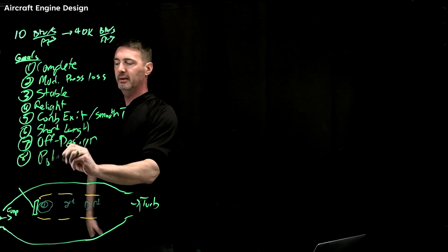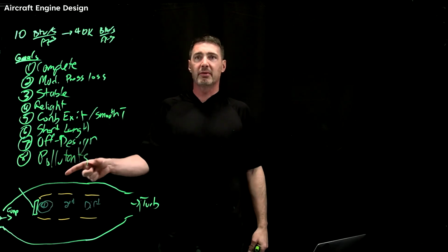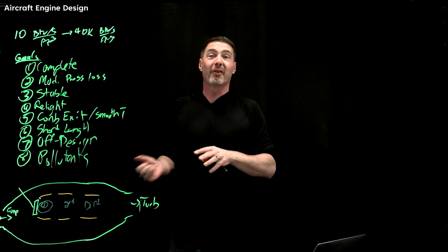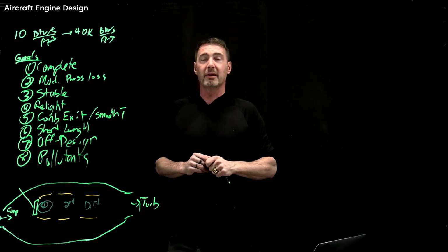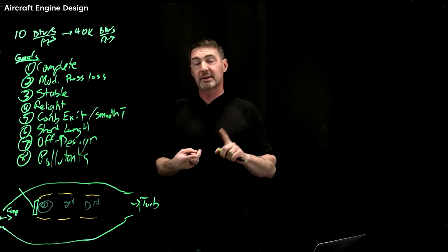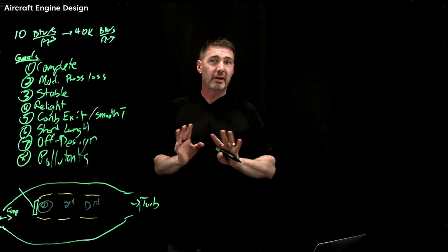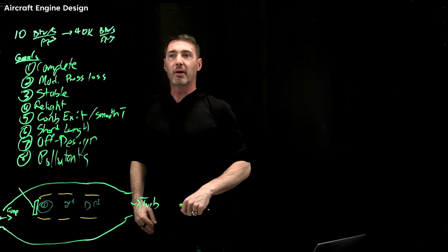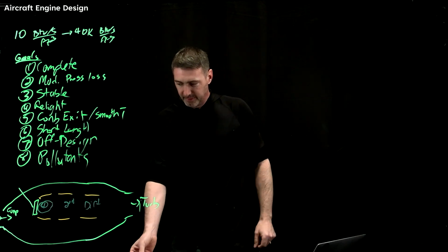Now, I know recently there's been quite the interest in CO2, but just to remind everybody, our interest about 30 years ago was all about NOx. And so that is still a requirement. We are still interested in NOx reduction because of our ozone layer and things like that. And so it's really this combination of generic pollutants. It's NOx, it's CO2, but it's also these unburned hydrocarbons. All of these things you have to take care of, and different regulations will drive that. Okay, so that's the main challenge with combustors.